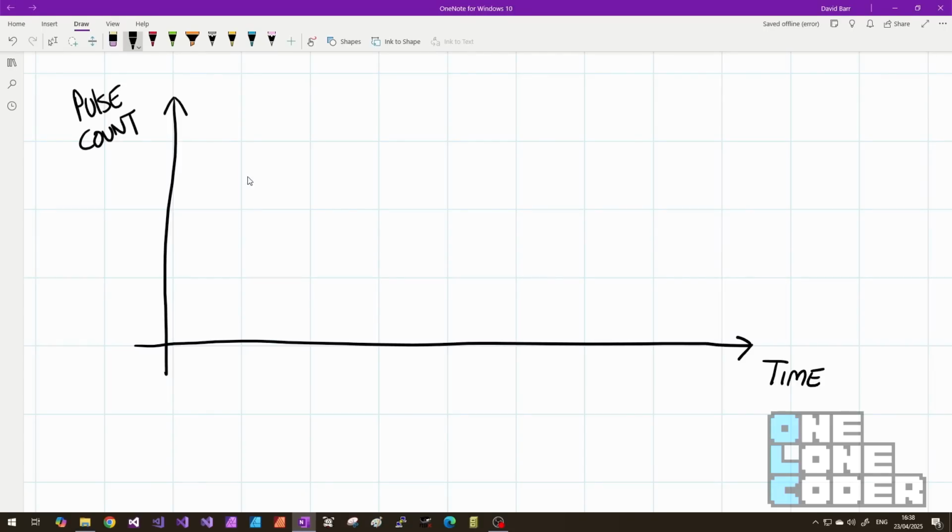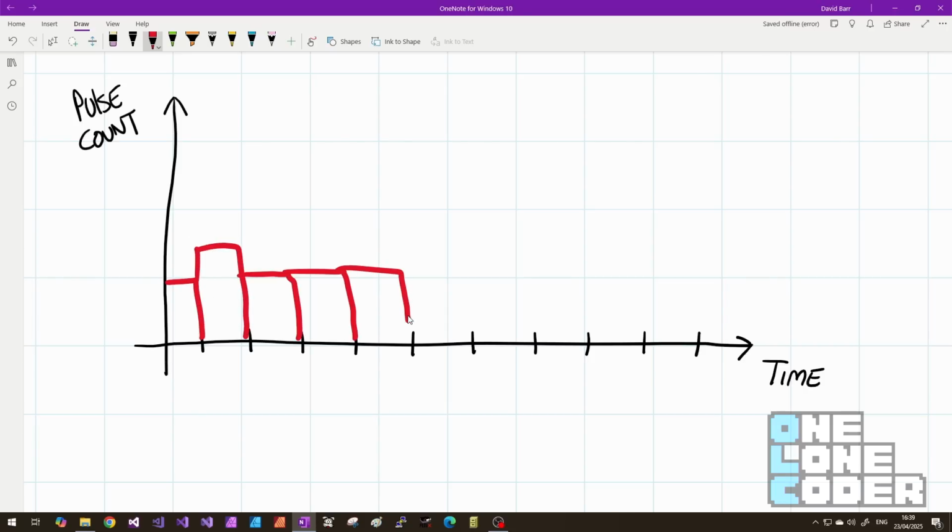As a first pass, the algorithm I'm going to implement is not clever at all. In fact, it's rather naive, and we'll see why later. Ultimately, I'm going to break time into 1 second intervals. For that 1 second, every time the LED on the smart meter blinks, I'm going to count it. And then I'm going to return how many counts there were per second to the server, which should hopefully yield a graph like this. Most of the time pretty similar, but when I switch the kettle on, suddenly it goes very high because we're getting a lot more pulses.